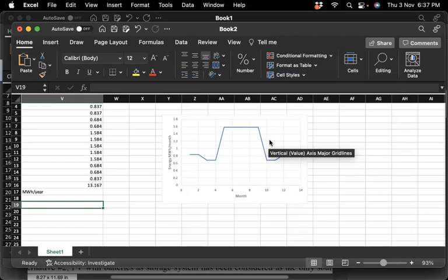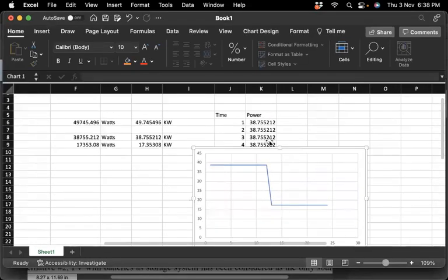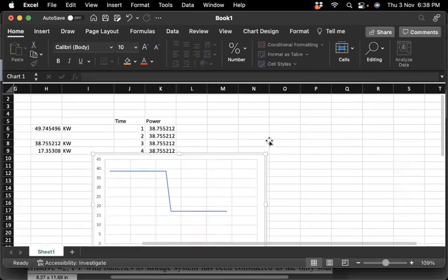Another example, if you consider normal sockets in an office building, this is what we can call a flat load or a uniform load. Normal sockets are usually used to supply, for example, computers and printers and all this stuff. And in an office building, you use this in both winter and summer. That's why this is what's called a flat load, so it will be some sort of a horizontal line. Again, if you return to our previous example, my dear students, which is this pump load, this pump load is relatively a constant flat load because this field is working in both winter and summer. So in both winter and summer, you have the same amount of energy consumption. That's why we call it a flat load or a uniform load.